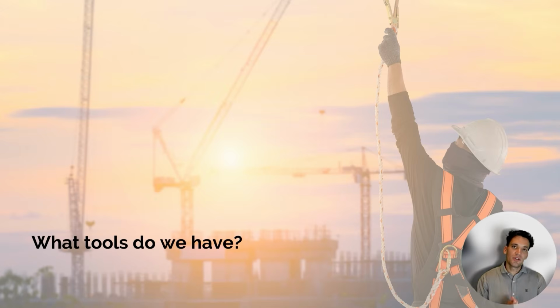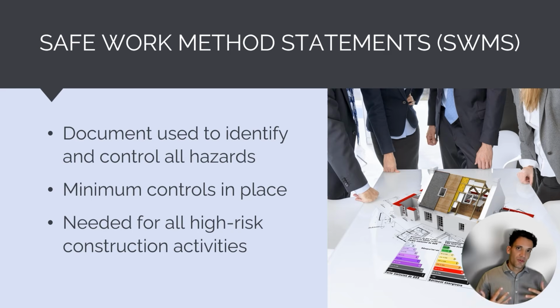Okay, so now I'm going to talk about what tools we have available to manage safety on a construction site. Okay, so the first tool we've got available is a safe work method statement, or a SWMS. So a SWMS is a document used to identify and control all of the hazards. So we walk through a construction activity, look at all the steps in the process, and against each of these steps, we identify the hazards and the control we're going to put in place.